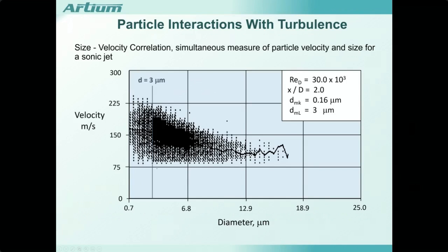But getting back to this, the turbulence fluctuations shown here for the small particles seem to capture the turbulence intensity, so that those fluctuations in velocity are representative of the large-scale fluctuations or the turbulence intensity of the flow. As we move towards larger particles, those fluctuation velocities are suppressed. These particles are not responding to the high velocity excursions in the flow. So using a larger seed particle, you're not going to get very good turbulence measurements.